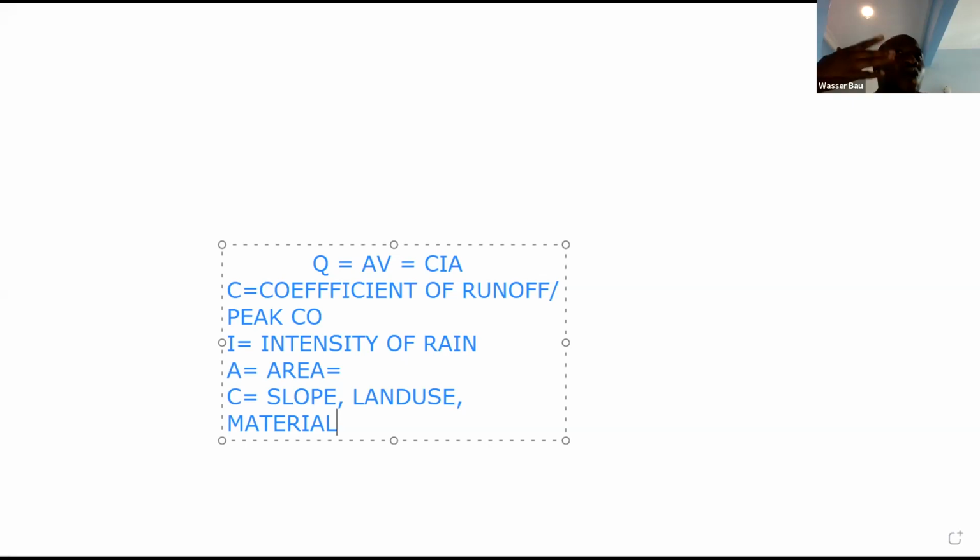So some of these areas like Enugu have a lot of clay materials as their soil. So when water falls, you see the whole water flowing on the streets because the clay and silty materials have a permeability of 10^-8, 10^-10. In fact, some silty materials that they use as the core of dams have material sizes in the range of 10^-12. The normal one you call sand, used for construction, coarse and fine aggregates, they are 10^-4, 10^-2.